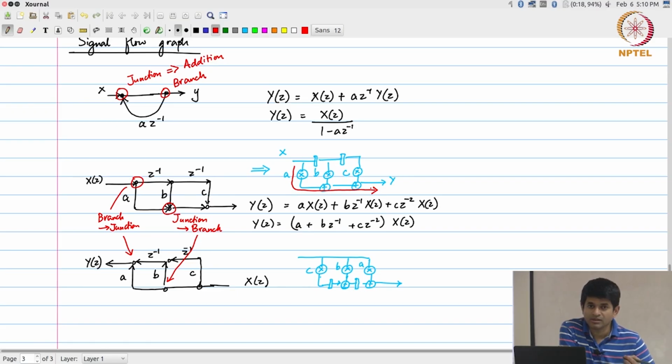Okay. Now that's because it's a 3-tap filter. If it had been a 10-tap filter, it would have been a multiplier followed by 9 adders. In other words, all those additions would end up being on the critical path. Now, should you really do them as a chain of 9 adders, or can you do them in certain other ways by creating some kind of a tree structure and so on?